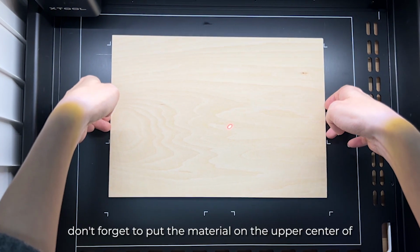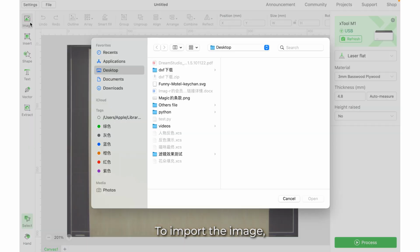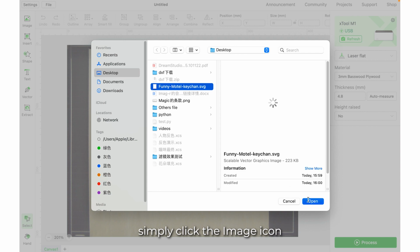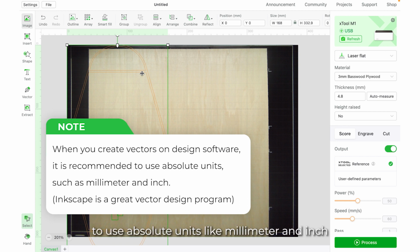Also, don't forget to put the material on the upper center of the base plate to reduce deviation and get a better engraving result. To import the image, simply click the image icon and select your desired image from your folder. Please be noted that sometimes the size of the original image will be changed in XCS. This is largely because a relative unit is used in the image, such as pixel, px. It is recommended to use absolute units like millimeter and inch. In this case, the size displayed on canvas is the same as the original design.